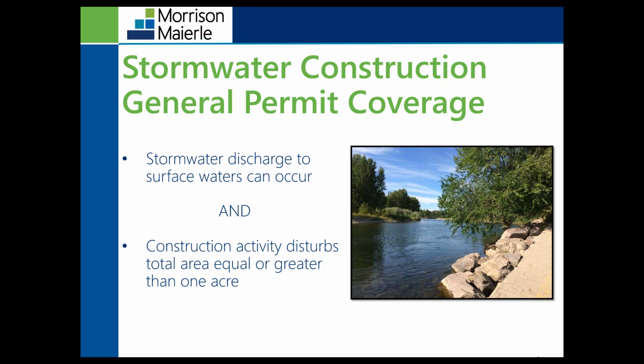And with this permitting, there's some requirements on discharging pollutants with that stormwater. So to be compliant with this permit, we're going to have to minimize the amount of pollutants discharged from your site. We're going to reduce those. DEQ has a requirement regarding discharging to surface water. Surface water includes any body of water, irrigation system, or drainage system, either surface or underground.